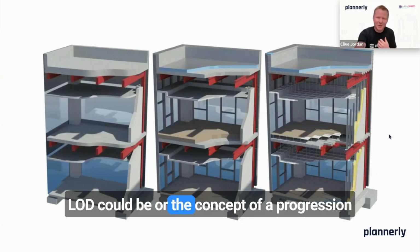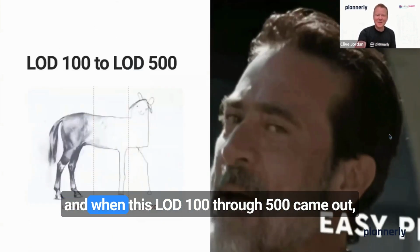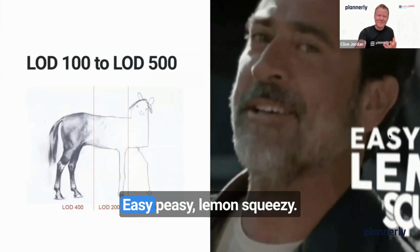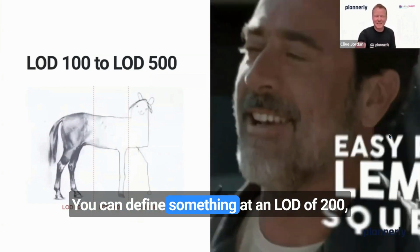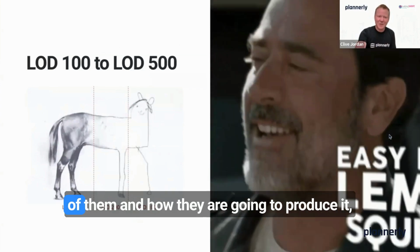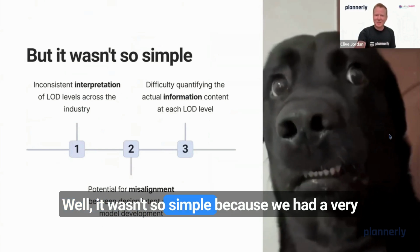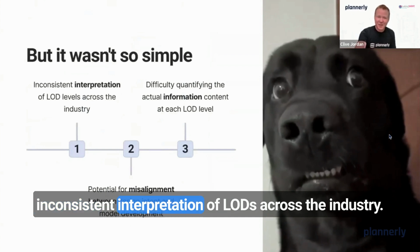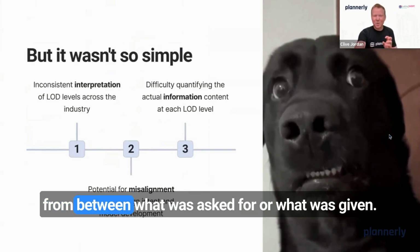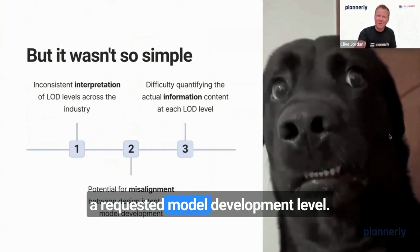When you look at it like this, it makes sense. The concept of a progression of a model could be one of these three states. And when LOD 100 through 500 came out, obviously that made sense. Easy peasy, lemon squeezy. You can define something at an LOD of 200, and everybody should understand exactly what is required of them, how they are going to produce it, how long it's going to take them, etc. Well, it wasn't so simple, because we had a very inconsistent interpretation of LODs across the industry. They were misaligned between what was asked for and what was given, whether it's design intent or a requested model development level.